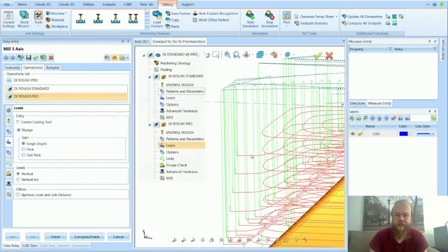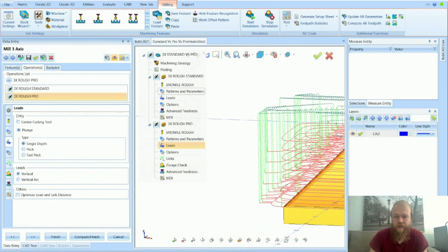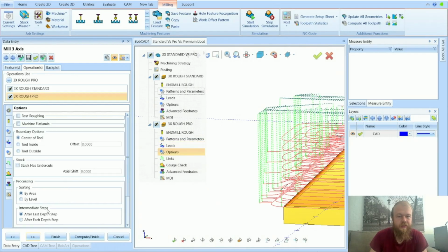So this is our side roughing option, where we're just using the side of the tool. We're not plunging the tool down in, ramping or anything like that. We're starting from the outside. We're plunging down from the outside of the stock, and then we're coming in with the side of the tool. That is offered in the 3-axis Pro. Same with the trochoidal high-speed machining options.